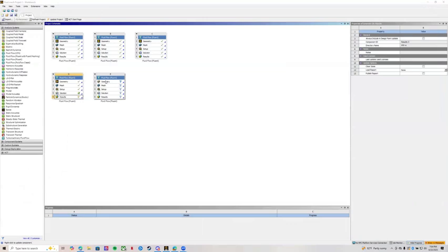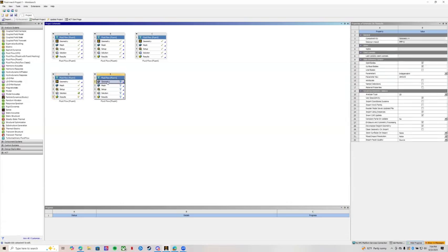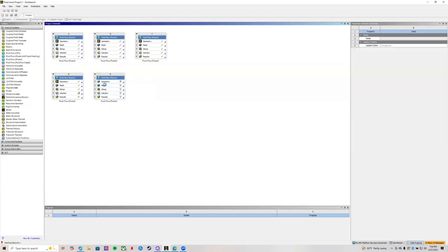Okay, so next thing we're going to do is this flow system is going to be for both our Couette and hybrid, because we're going to use the same geometry and meshing. I will just be changing the setup, solution, and results sections. So we're going to go into our geometry, which, remember, you click to go to Model, not to Discovery, like this. Discovery takes a long time to load and is not really what you need to use to make a sketch for the pipe system.